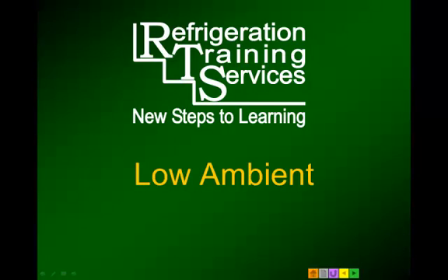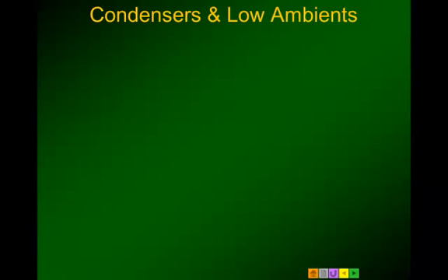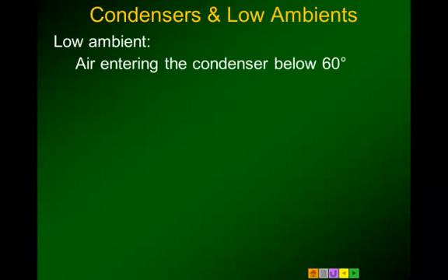In this presentation, we're going to be looking at low ambient conditions and how that affects the refrigeration equipment, and then what can be done about it. Condensers and low ambient. Low ambient is considered any time the air is entering the condenser below 60 degrees Fahrenheit.